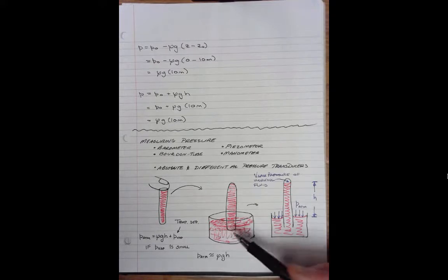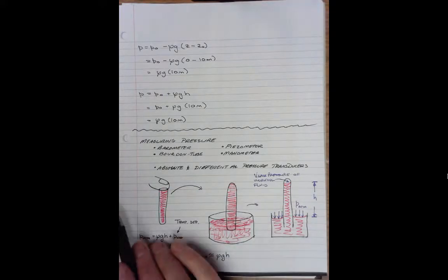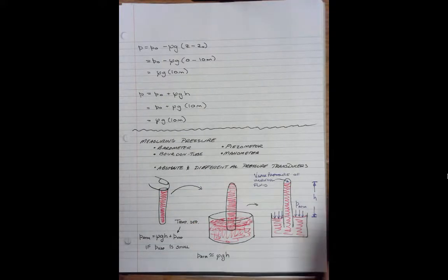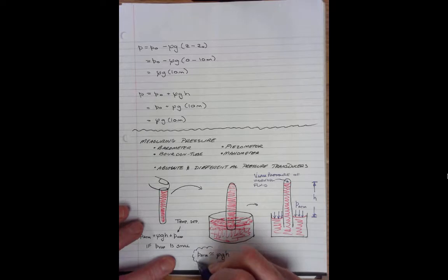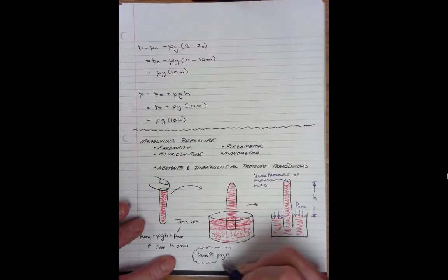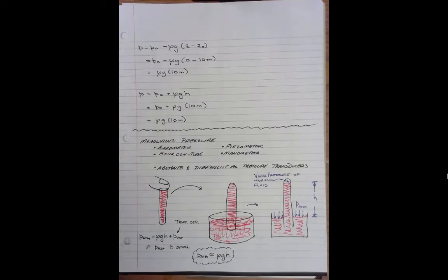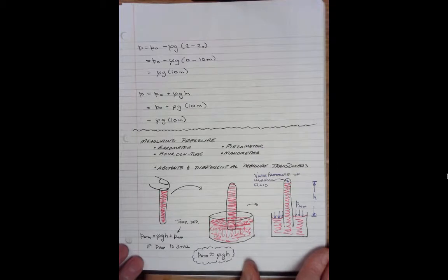So this type of barometer is a fluid type. There's also things called barometers that are based on Bourdon tubes, and things called barometers that are based on pressure transducers. They're all doing the same goal, which is to give us a tool to estimate the atmospheric pressure, which comes in handy, especially if we're having to switch between gauge pressure and absolute pressure.